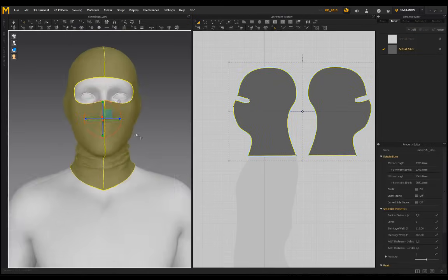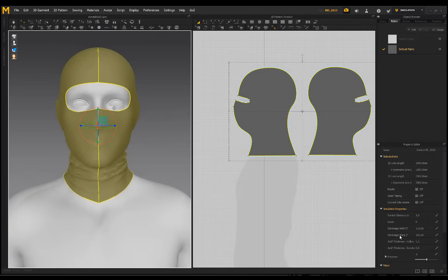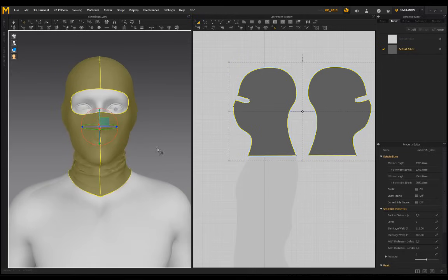But basically where the magic came in for getting more wrinkles was, you can see over here, if I've got both patterns selected, my shrinkage weft is by default on 100. And if you increase that value, it's basically like adding more fabric onto your garment. So that's exactly what I did. I put it on 115. And if you had to put shrinkage warp on 115 as well, it's basically like increasing the size of the pattern. So it makes the garment bigger as well.